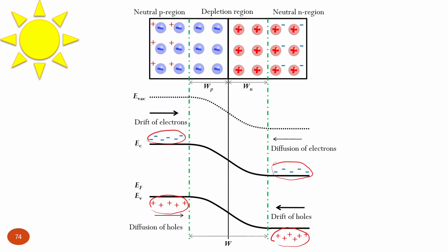So, coming back to our previous discussion, we claimed that drift current is small because of the low concentration of minority charge carriers. But what happens now? Drift current will significantly increase because the concentration of minority holes and electrons in the N and P regions significantly increased because of photogeneration. So these are minority non-equilibrium charge carriers already. Their concentration is much higher, and this drift current increases a lot.